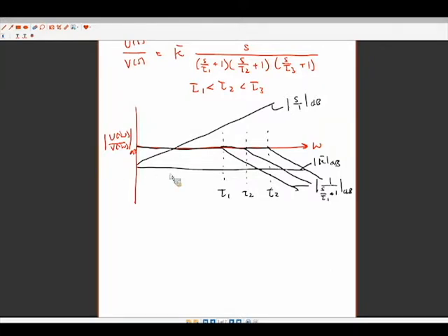Okay, so we have a pervasive change in the magnitude from the gain. We also have this pervasive 20 dB per decade slope. So that means at low frequencies this magnitude plot is going to go through this point. I just basically draw this down here. Okay, so I'm going at positive 20 dB per decade. As soon as I get to that first pole, it's going to go from a slope of positive 20 to 0, right? Because I've taken positive 20 minus 20. Okay, that's the slope of 0.